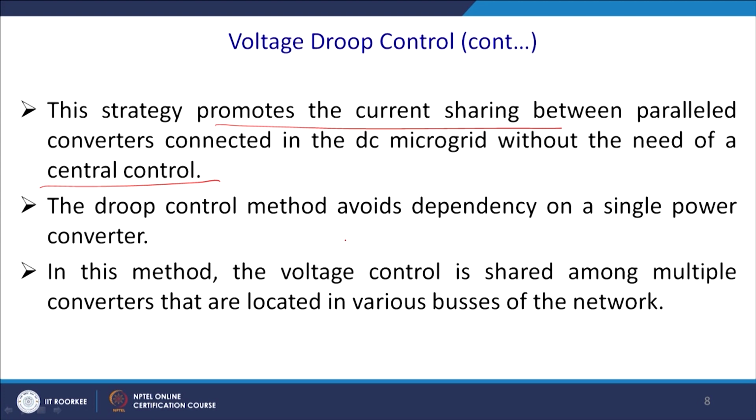The control method avoids dependency on a single power converter. If the master controller goes out, then it is a total blank, you do not have any redundancy. But here in this case you have a huge redundancy. So, whosoever can take care of the load, it will take care of the load. Because there is no concept of the pilot